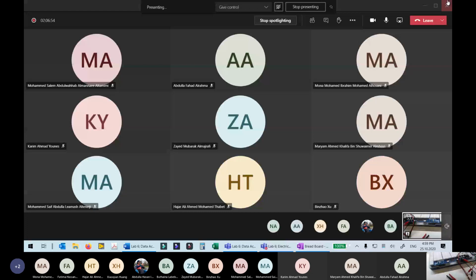Now the same here, the Elvis has that, but I see just 3 terminals. You see here, this is the digital multimeter, and there is V, omega, and diode. This terminal is used to measure voltage, resistance, and forward bias for a diode. This is the common, and this is the current measurement terminal. Guys, you get it? We can repeat and spend time on this until you feel comfortable. It's important to understand multimeters.